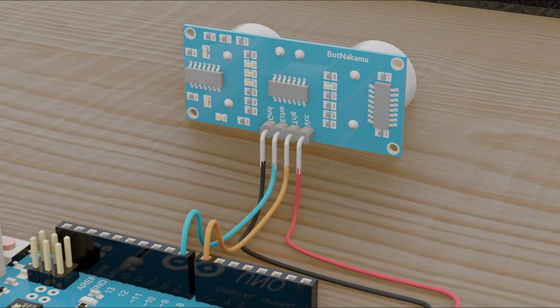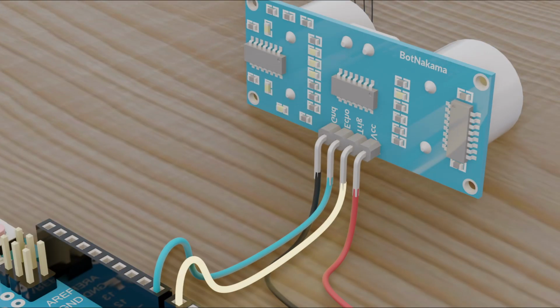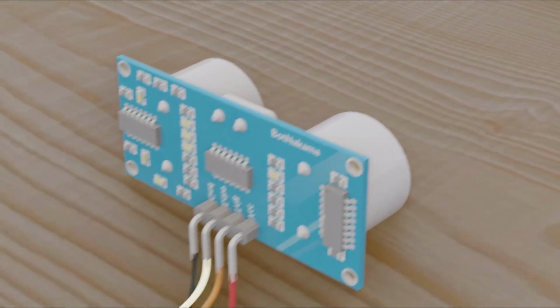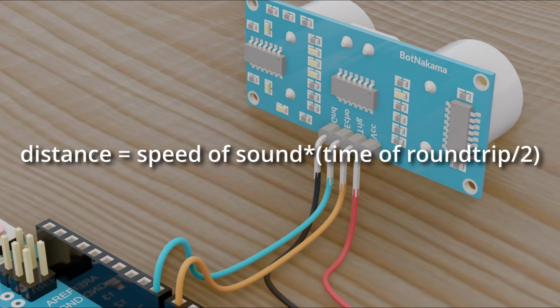Take an ultrasonic sensor, for example. For this specific one, we can use an Arduino's digital pin to send a voltage signal to the sensor's trigger pin, causing the sensor to emit ultrasonic waves. Right when it does that, the echo pin turns on, sending a voltage back to a separate digital pin, and when the ultrasonic wave returns to the sensor at its receiver, it turns off the echo pin. The time between the echo pin turning on and off is how long it took for the wave to make a round trip. And we can use that to calculate the distance with a basic formula with speed and time.